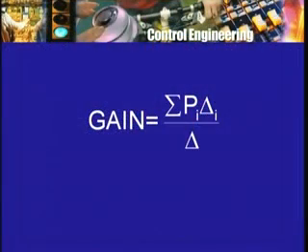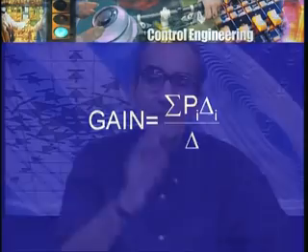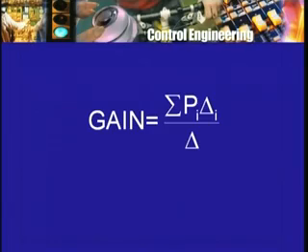Now what does delta i stand for? Delta i stands for what remains from delta if we remove those loop gains which touch the path Pi, whose gain is being multiplied by delta i. So choose a forward path, find what remains from delta, multiply them together, then go to another forward path, find out what remains of delta for that forward path, multiply those together, add up, and so on. So understand this sigma Pi delta i divided by delta properly, so that you don't go wrong. It's not enough to write an expression, one must know what it means.